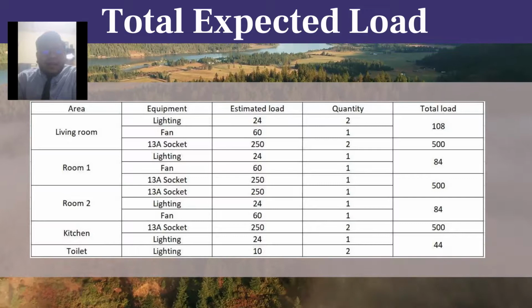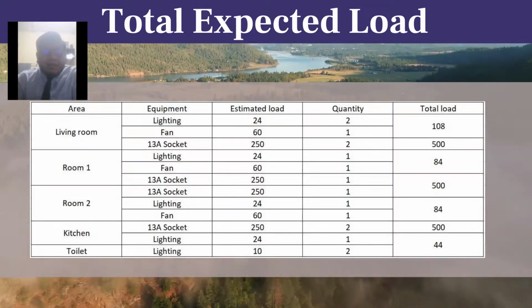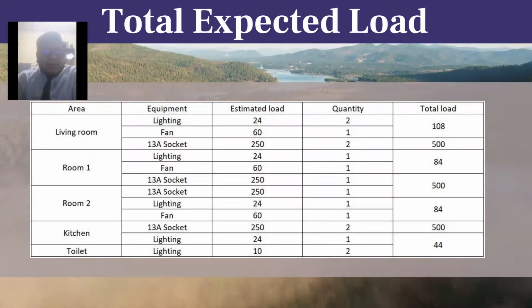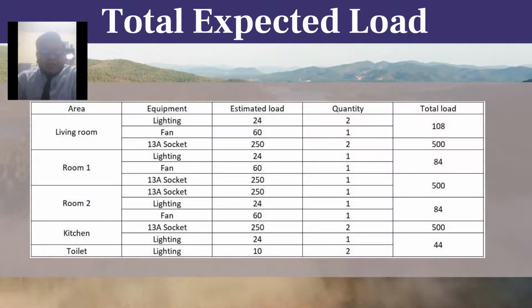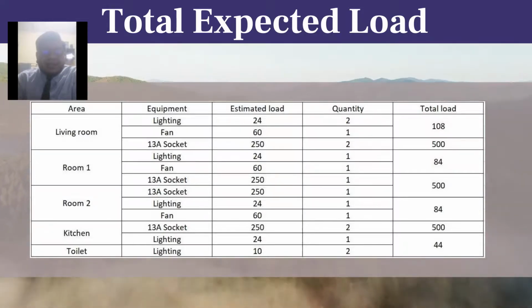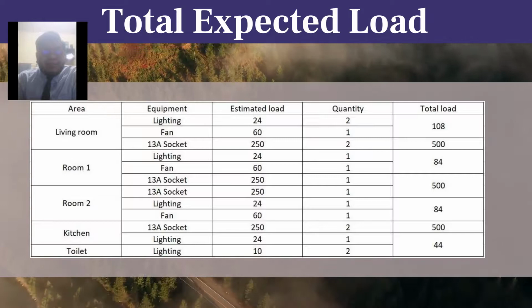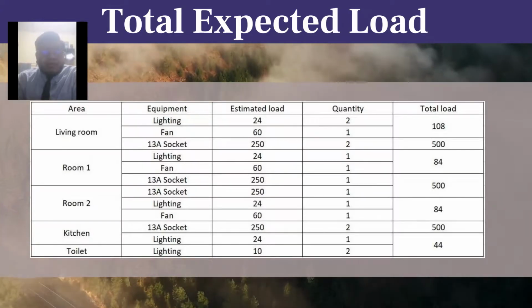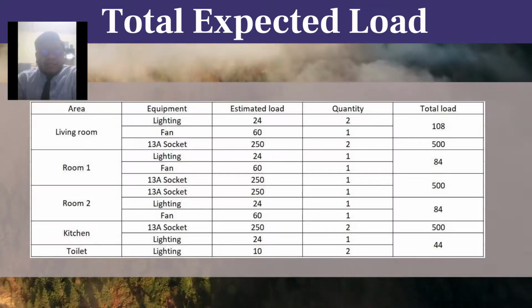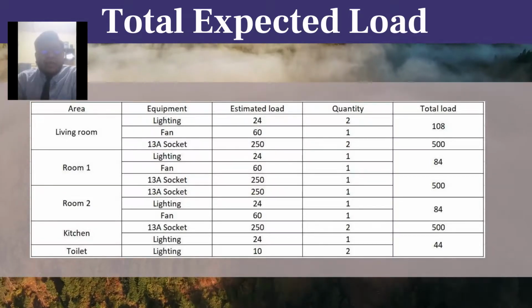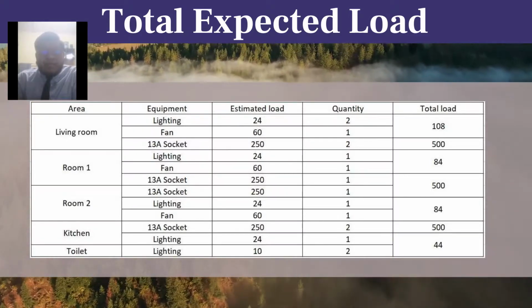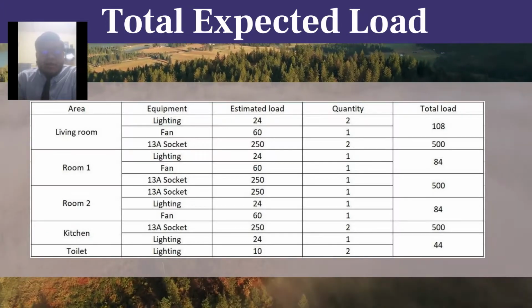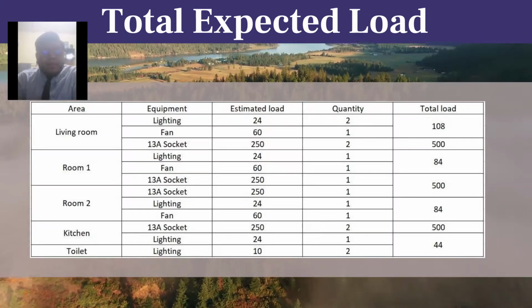In designing a house wiring plan, there are a lot of things that need to be considered, such as type of lighting used, size of cable, current rating and molded case circuit breaker, current rating and number of miniature circuit breaker. For the lighting, 2 types are usually used to light up the room and a certain area, such as fluorescent lighting and LED lighting. In this case, we use fluorescent light because the rural area only has fluorescent light.